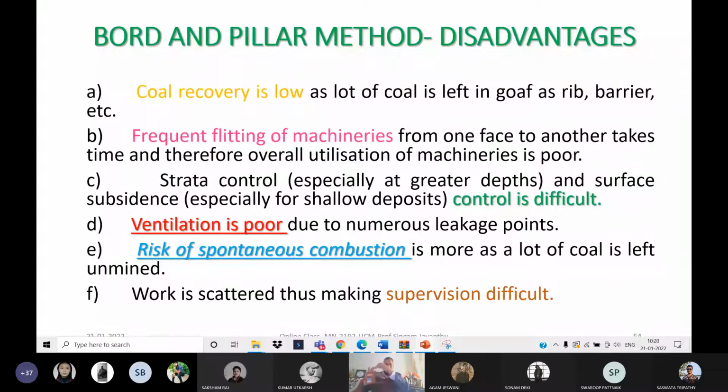Even the subsidence, compared to longwall, if it is a longwall panel like this, there is a uniform subsidence on the surface. It is coming on uniformly, right? Otherwise, in strata, when it is a board and pillar, in between we are leaving some ribs and other things. So there is uneven distribution, and somewhere tensile failure, somewhere compressive strain, tensile strain, right? And that causes a lot of cracks and other things. Okay, this is the meaning of this class C, whatever third I mentioned here.